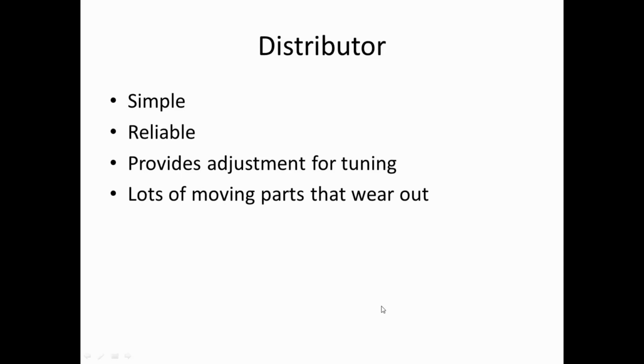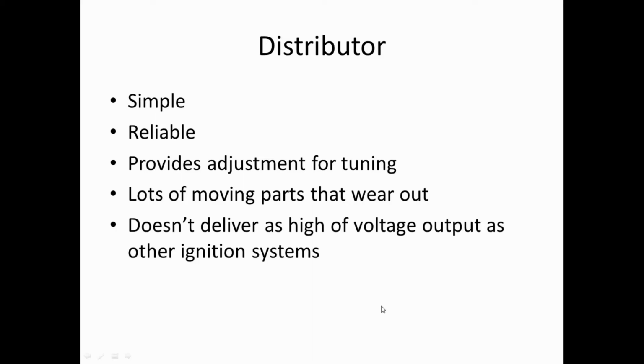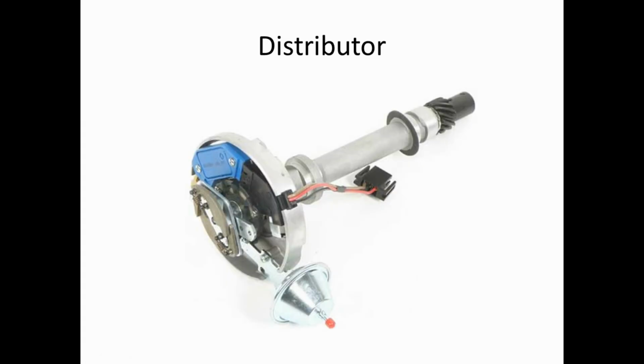But the only issue is there's a lot of moving parts that wear out. The cap, the rotor wear out, stuff like that. Spark plug wires, and Lord knows spark plug wires are not cheap. The only problem with this is it doesn't deliver as high of a voltage output as other ignition systems.